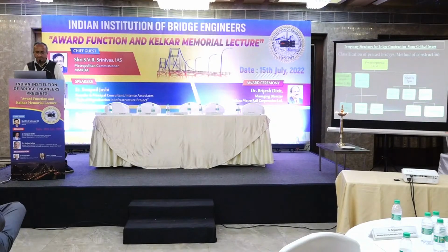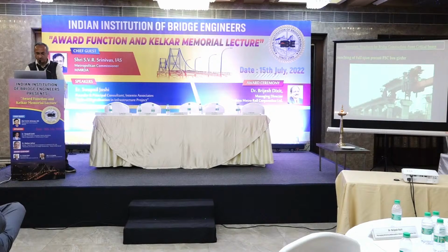Then we come to precast segmental decks: incremental launching, then cantilever construction can be done by using cranes, lifting frames, and gantries. Span by span construction can be done by scaffold, that is ground supported structure, or lifting frames, or launching gantries. So again, an example of a full span box being launched by a sophisticated launching girder.